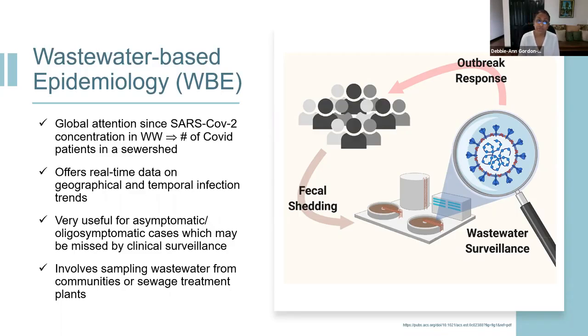Well, in wastewater-based epidemiology, the prevalence of the virus or the infections in the community could be estimated by enumerating the virus RNA in the sewage and then performing mass balances on virus shedding and using population and sewage flow rate data. So we can use this information then to inform public health responses to the outbreak. And that is the reason I'm giving this talk, because I'm hoping to garner some interest in this particular area of study.